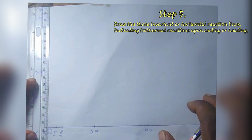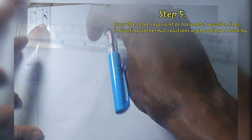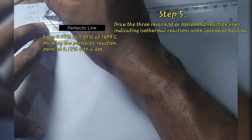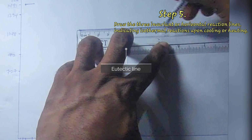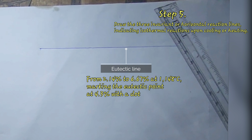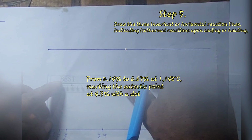Step 5. Draw the three invariant or horizontal reaction lines, indicating isothermal reactions upon cooling or heating. 1. Peritectic line. From 0.09% to 0.55% at 1493 degrees Celsius. Marking the peritectic reaction point at 0.18% with a dot. 2. Eutectic line. From 2.14% to 6.67% at 1148 degrees Celsius. Marking the eutectic point at 4.3% with a dot.